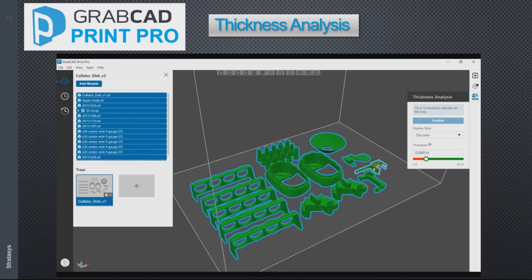Once we get up to about 40 thousandths of an inch though, this part here on the right, we start getting some red spots. So we've got a wall on this part that's about 40 thousandths of an inch. The rest of these parts on the tray are all pretty thick. So I could build the rest of these parts at about a 13 thousandths inch slice thickness. That would give us a minimum wall thickness of about 45 thousandths of an inch. So this part on the right here, I might want to take off and build on a separate tray or a different machine at a 10 thousandths inch slice thickness. The rest of these parts we could all build at a 13 thousandths inch slice thickness.